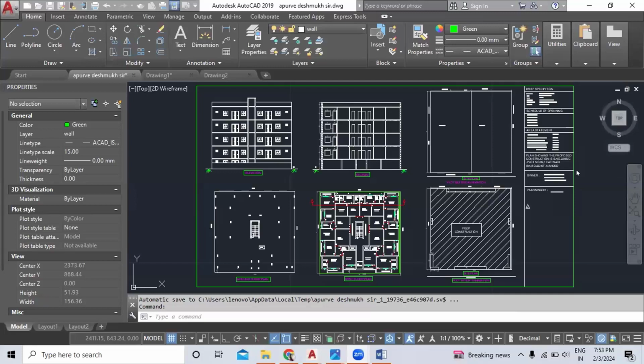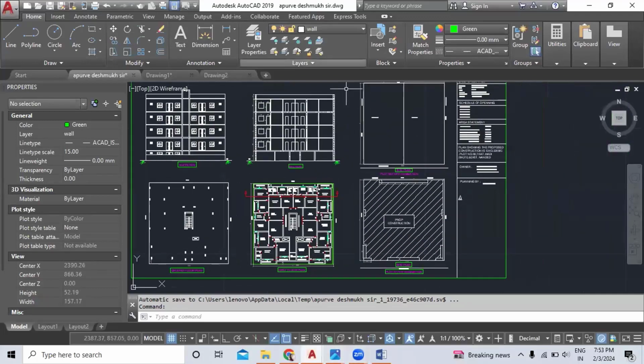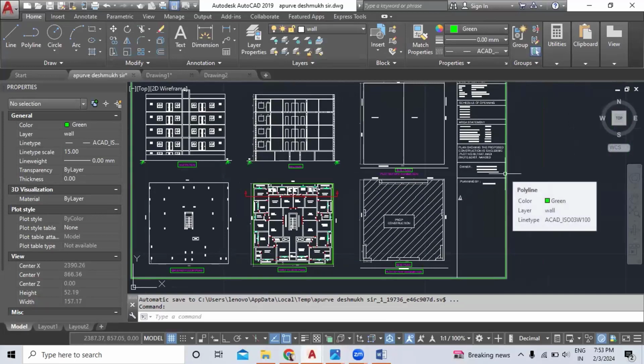The purpose of using purge is that it is the command where we avoid or delete unwanted MBs in our file or drawing. This is a DWG file, and behind our drawing there are lots of MBs that make the file heavy to share. So we use the purge command and delete unwanted things working in the background, and then our file will be much lighter to share. A file could be 100 MB for sharing by mail, so if you want to share the drawing file, purge makes it easy.